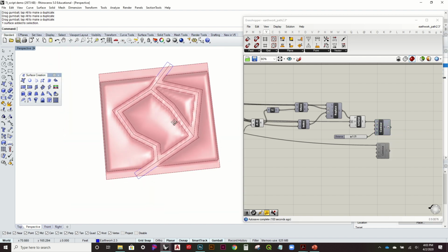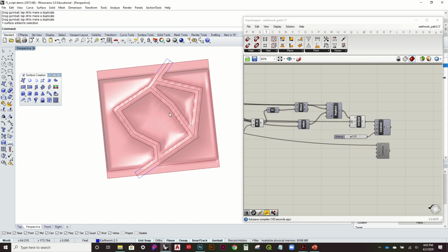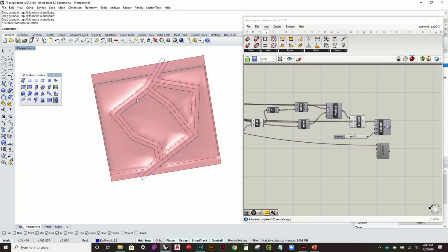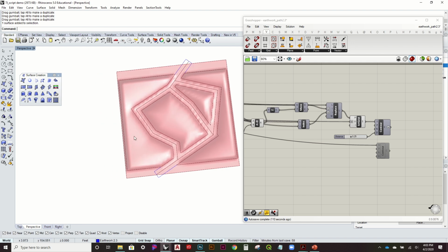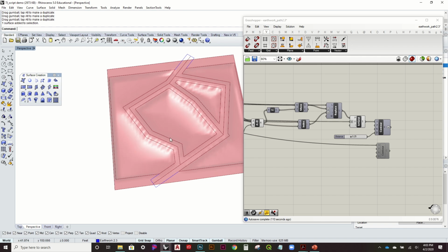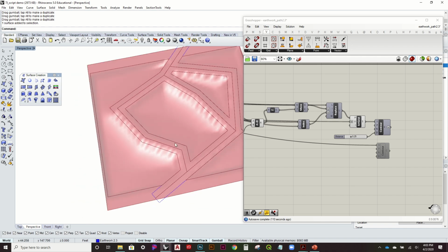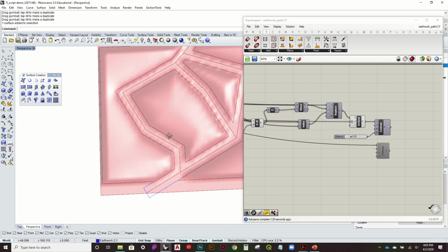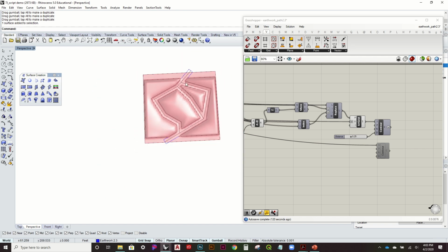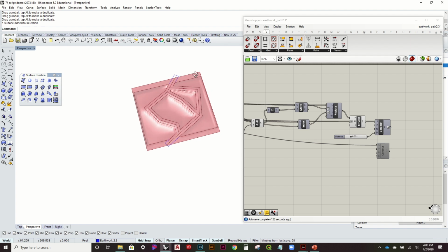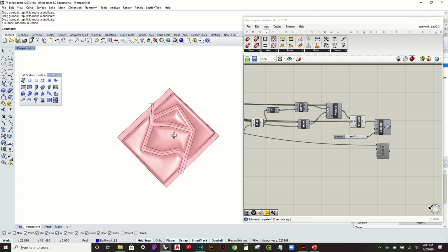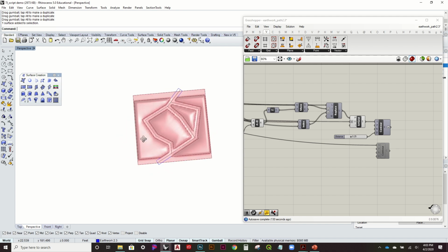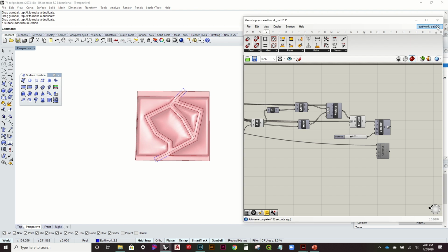And like I said, you can definitely integrate the design of the pathway in Grasshopper, but honestly, I think you could do it much quicker in Rhino. Obviously, you can do some of the other modifications to the pathway, like the railings and stuff, pretty quickly in Grasshopper. But to get the actual geometry, it's pretty easy to just do that in Rhino. I know a lot of my videos emphasize the workload being in Grasshopper, but in this case, it's a little change of pace. So let's take a look at how to do it that way.